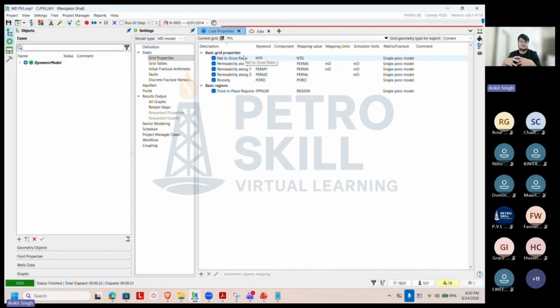This is where you define your simulation case. Now your static part is converted into the dynamic part. Now the simulator must understand the dynamic part, what its requirements are. For instance, I am going to define what my grid is. So NTG defines the structure of it, perm-x, perm-y, perm-z, and porosity define the property inside it. All right, and then fluid in place is basically the region specification.